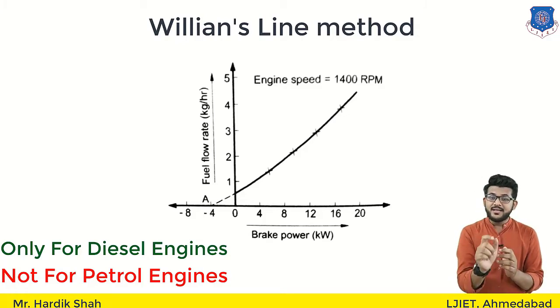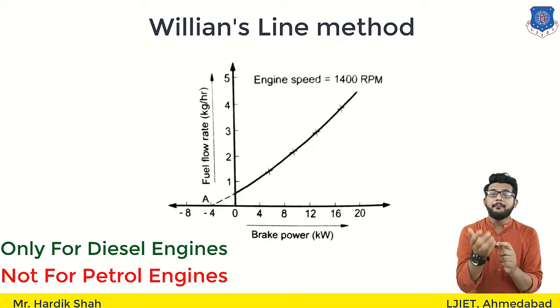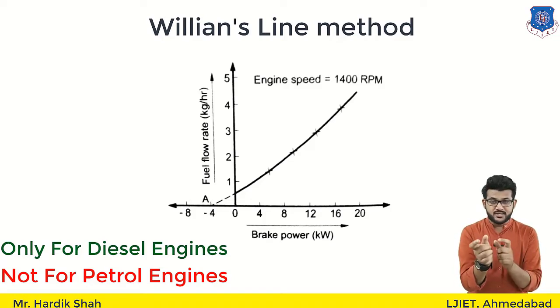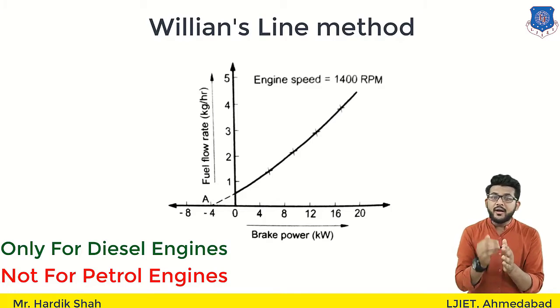In a diesel engine, we draw a constant volume of air, or compressed air, and vary the fuel injection. So technically, we alter the quality of the air-fuel mixture. This is called qualitative governing.